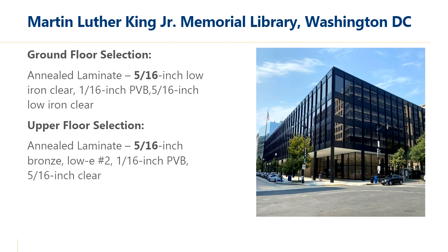Once these went into production, I'll just note, you can see the 5/16 in bold here. The glass thickness was increased from 1/4 inch to 5/16, as the manufacturer said that was the minimum thickness they felt comfortable handling at the glass sizes, which were about 9 feet by 10 feet. So nothing to do with performance per se, but rather with constructability. And as part of the decision-making process, we also did take a look at those thermal stresses that Mark mentioned.